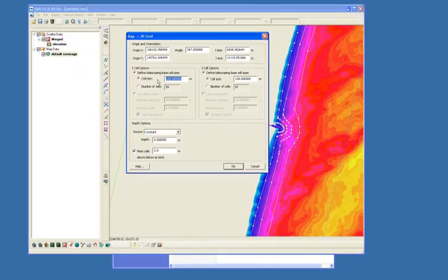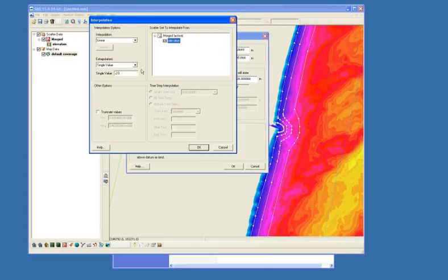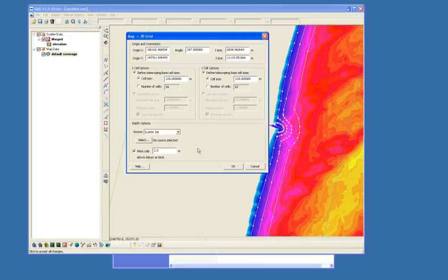Give it a largest cell size in this block, and then specify where your depths are coming from, just like we did yesterday. Extrapolation distance or value, and then marking certain cells above the water level as land, and I think we chose 1.4 meters above water as land.